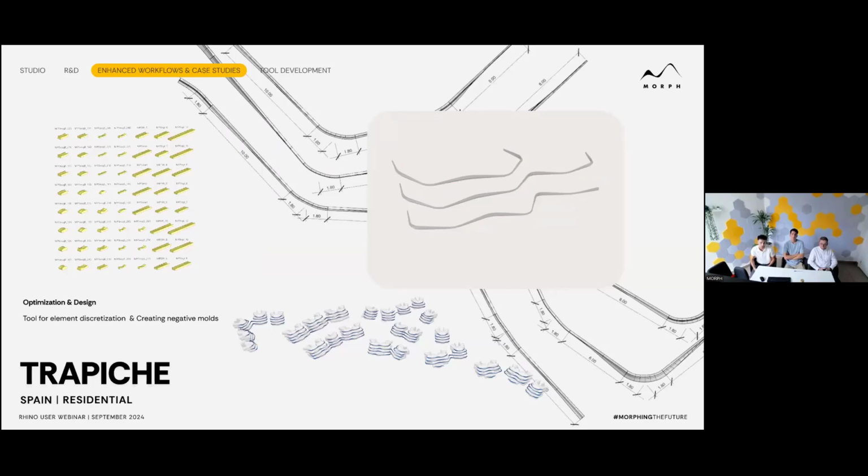We had 35 different building blocks to fit, so divide and conquer. We condensed all the cases in just 3 different singular cases that were repeating all over the project. For each of these singular cases, we created a script that, relying on Kangaroo, was automatically rationalizing all these outlines and baselines.